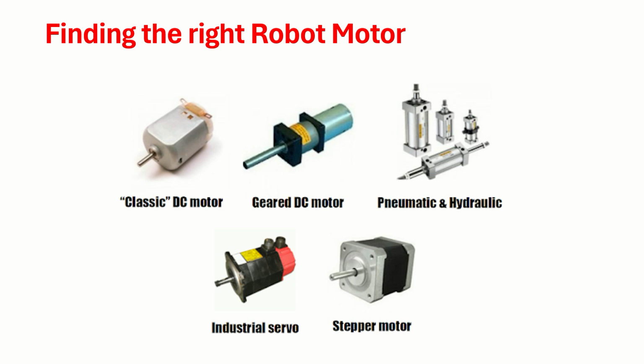The other types of motors you can also use are an industrial servo motor or stepper motors. So there is a difference in the principle of working. In case of a servo motor, the principle of working we will discuss in the subsequent slides, where the displacement and direction of a servo motor is done with the help of the pulse width of the pulse.